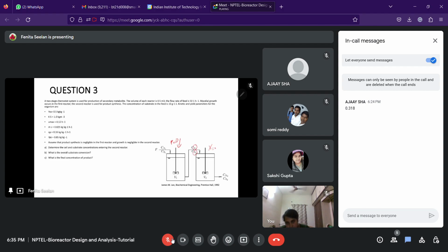Always keep the same units when you are solving the problem. Here, I think it is all in kilogram and meter cube. So let's convert whatever is in grams to kilogram per meter cube. It will be helpful; if we convert the data first, it will be easy for us.